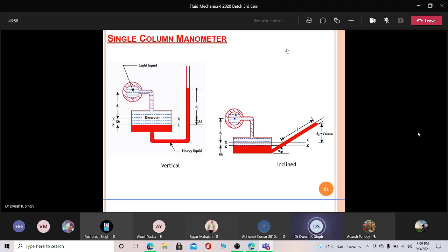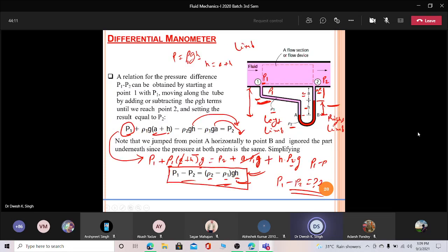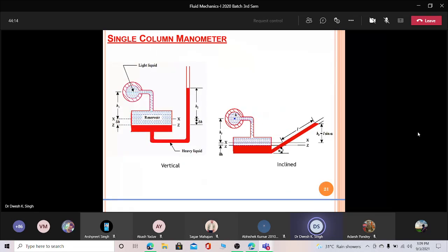Okay, so there is some other manometer also here. What is the difference? There is some reservoir here. Okay, the concept is the same, like which we have discussed here. The piezometer and manometer are based on the balancing of the liquid. They all work on these concepts, balancing of liquid in one column or in two columns, like one limb or two limbs. The basic concept is the same. What happens is there are some slight changes in the geometry.